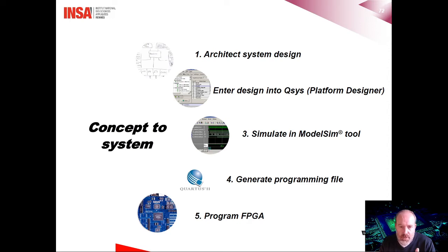The generated files can be used in the hardware description following the classical design flow in Quartus. For example, it's possible to simulate the architecture using the functional simulation first, using ModelSim, for example. Then the classic design steps, such as synthesis, place and route, are performed nearly automatically. An additional timing simulation can also be performed to take into consideration all the timing, delays, etc. If all constraints are met, then designers may generate the programming file that is going to be downloaded into the FPGA. The bitstream file has the .sof extension in the Intel environment. You will see that later in the lab.